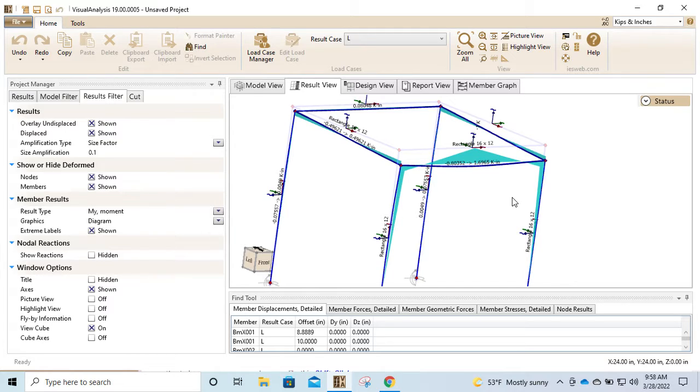Like on Adam's example with the rafter thing, the plate was only connected at those 4 nodes. The displacement of that plate would not induce any load on those, because underneath, the elements are only connected at the nodes, so it just displaces through the element. Yep, you would look at a displaced shape diagram like we just did here, and it would go right through it.